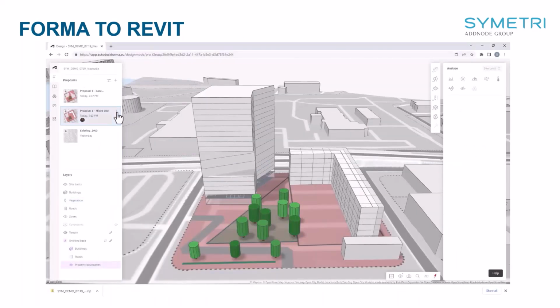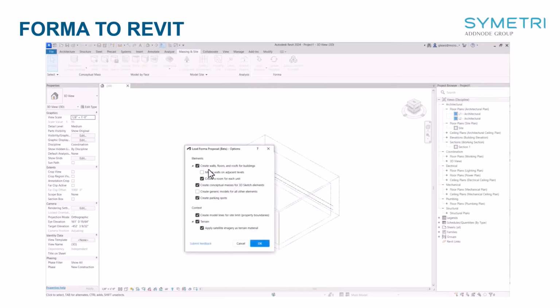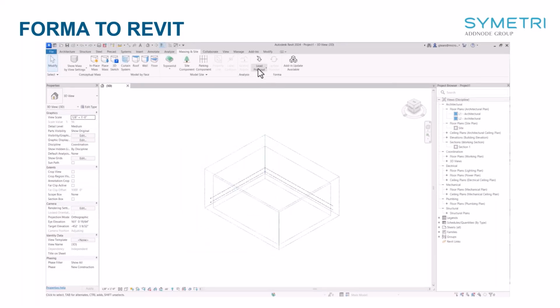All right, quickly we'll go over Revit export. You do have the ability to export out to OBJ. It's not as data rich. It's just an OBJ 3D model. But with Revit, we can send that immediately from Forma to Revit under the Massing and Site tabs now. And you can choose your options or what you decide to load in.